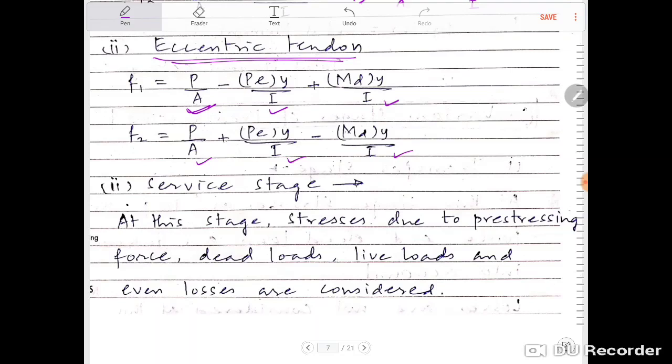Okay, what about the service stage? At this stage, stresses due to the pre-stressing force, dead loads, live loads, and even losses are considered. So whatever stresses are there in the transfer stage, in addition to those you are also going to consider the stresses due to live loads and losses. You are going to consider the pre-stressing force, dead loads, live loads, and even losses in the service stage.